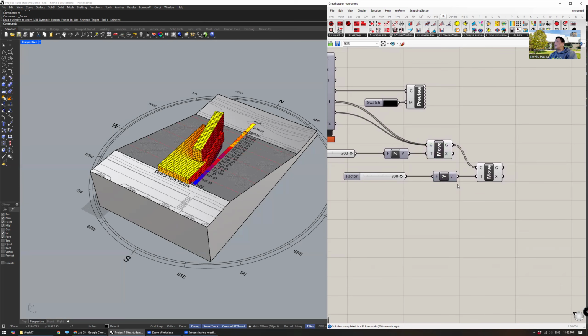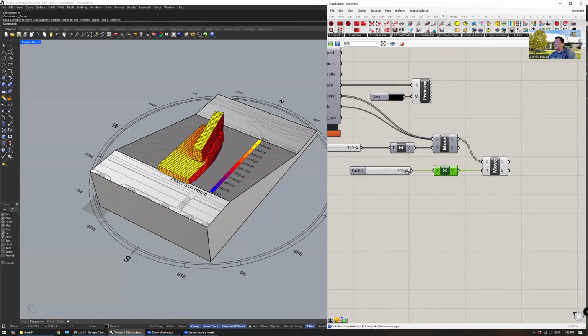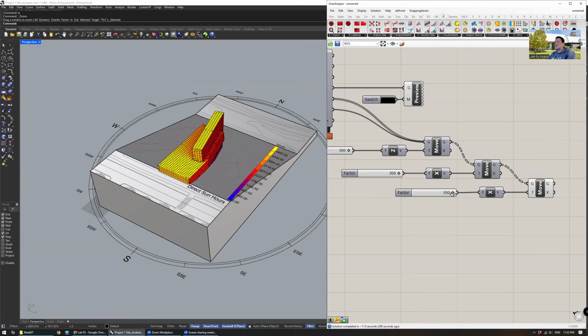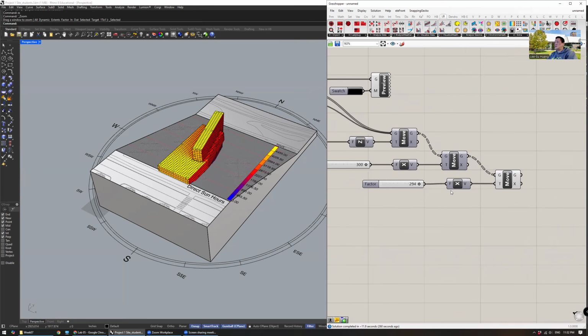oh, actually probably, sorry, go from here to here, the geometry, X, so sorry, unit X, it should be unit X, hide the original, so this can move it out depending on how far out you want to move this. And if you want to move it down, then it's just unit Y, again Control C, Control V, and just daisy chain it, so G, G for all this, going out. Hide the previous one. And this just gives you a bit more control. And you, of course, replace this with Y.